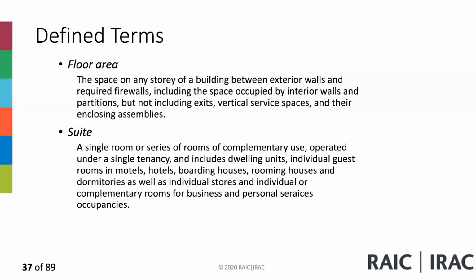So floor area is the space on any story of a building between exterior walls and the required firewalls, including the space occupied by interior walls and partitions, but not including exits, vertical service spaces and enclosing assemblies. So this is important when you're looking at floor area and occupant loads. You look at the space occupied by the interior walls and partitions, but you don't look at the vertical service spaces, exits, and their assemblies.